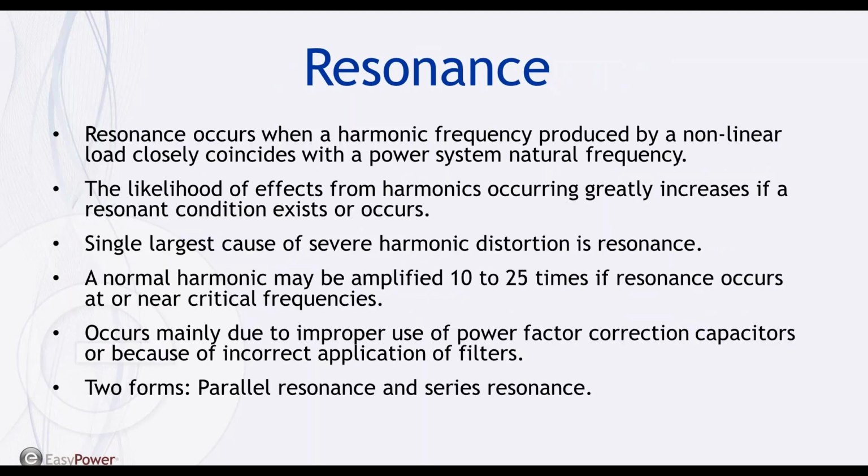Another phenomenon related to harmonics that can occur is system resonance. Resonance occurs when a harmonic frequency produced by a nonlinear load closely coincides with a power system natural frequency. The likelihood of effects from harmonics occurring greatly increases if a resonant condition exists or occurs. The single largest cause of severe harmonic distortion is resonance.